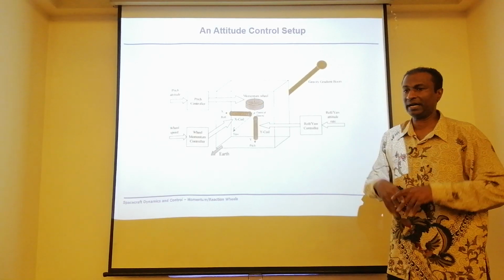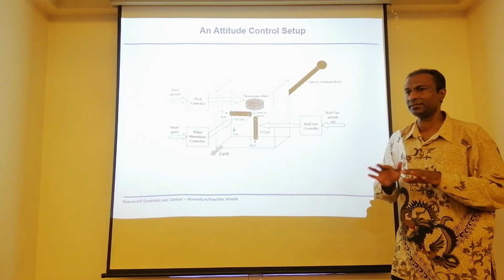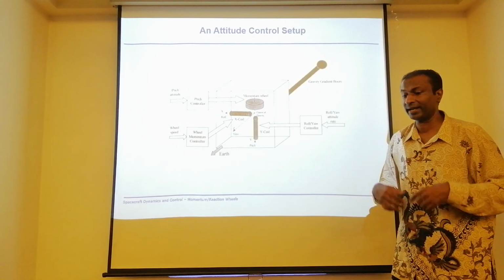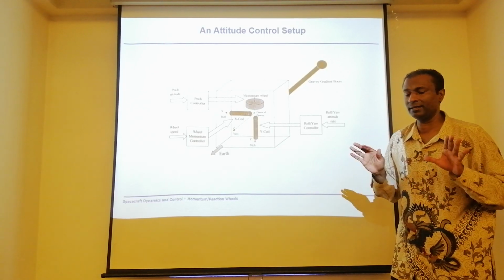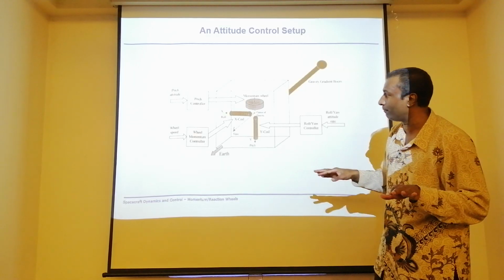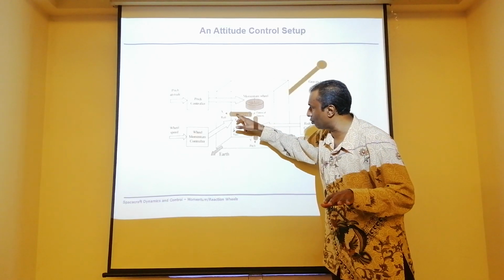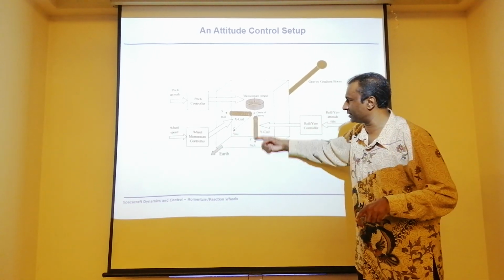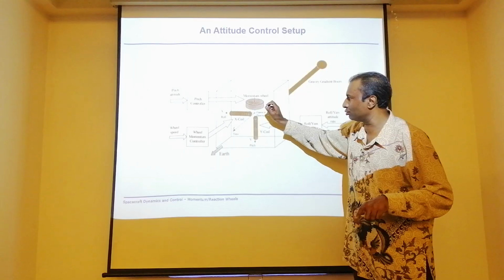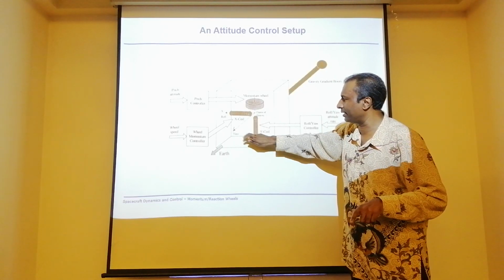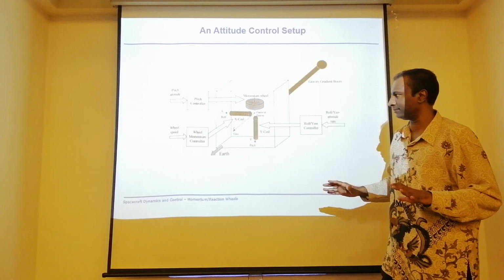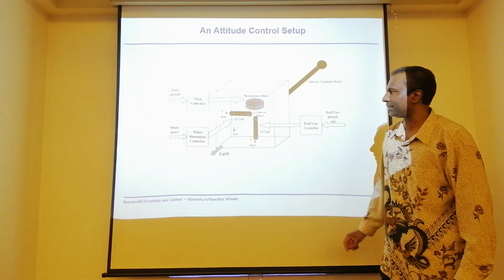Momentum wheel. I have a momentum wheel, that means what? My pitch axis is done. Pitch axis, I have active control already. Then I can provide passive control, or rather gyroscopic stiffness, for roll and yaw. The pitch axis can produce roll and yaw passive stiffness. Done.